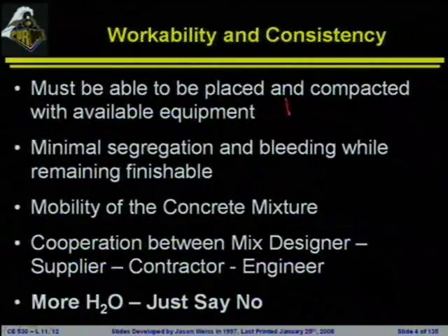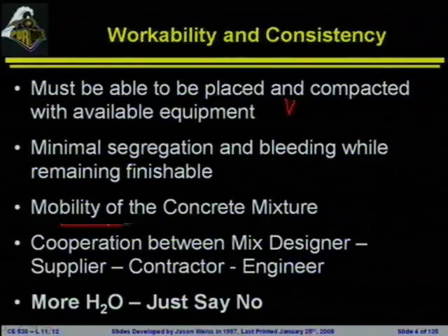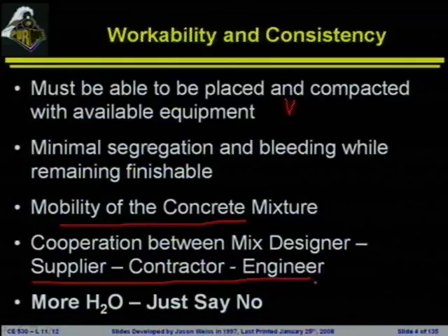It has to be able to be placed and compacted with the local materials. All right, the local materials, local equipment are incredibly important. Mobility of the concrete mixture is going to be important, especially in difficult applications. And there has to be cooperation between the supplier, contractor, and engineer. Some of you will have seen that the Indianapolis Library is ringing bells in the Indianapolis Star. This is a prime case of a concrete that doesn't go into the forms very well and leaves quite a few gaps. Lack of communication between the supplier, contractor, engineer.